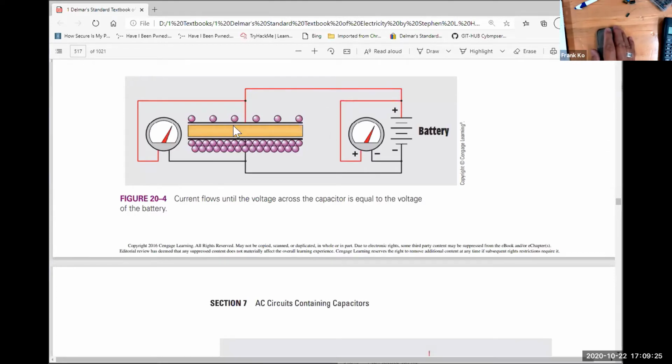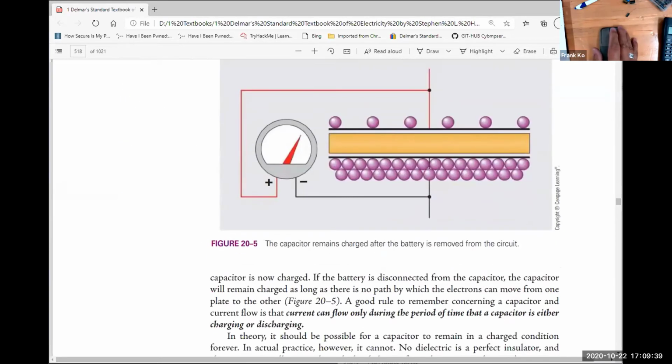So capacitors will store whatever the capacitor charges up to. If this is a 12-volt battery and this is charged to a full 12 volts, then I will be able to measure 12 volts on that capacitor. Now, once I remove the voltage source, I will still be able to measure that voltage on the capacitor, because a voltmeter will not discharge the capacitor. The voltmeter has an insane amount of ohms, so it will not discharge a cap.